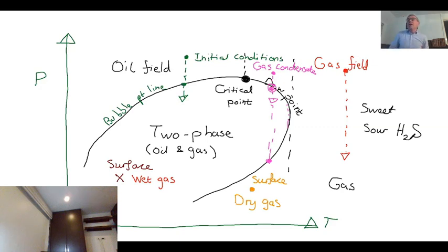So what you normally do is you can use amines and essentially dissolve away the more acidic components, and they're retained, and then you can heat up these amines and the gas is released. And you might say, well, what do you do with this gas that you separate out? That comes at a cost. That's why it's not so desirable, because you have to separate it out. Interesting thing here is the separation of gases, H2S, CO2, has been around in the oil industry since the 1930s.